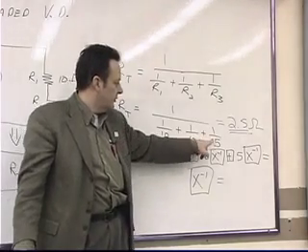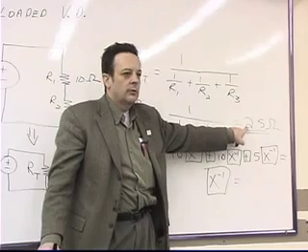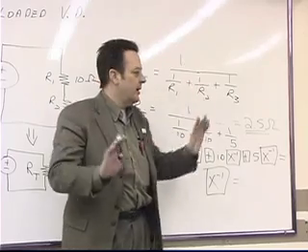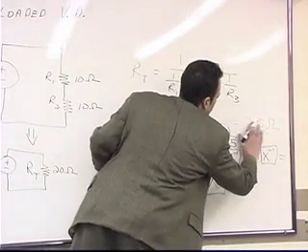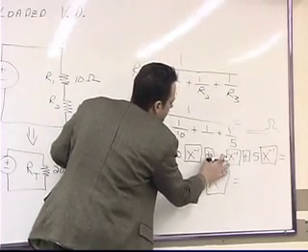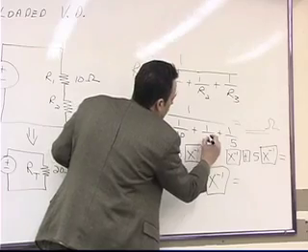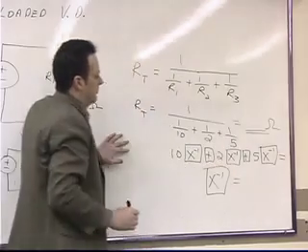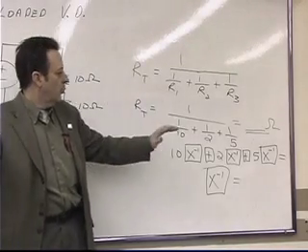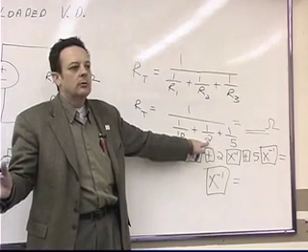Do you notice how the smallest resistor in the circuit was a 5 ohm resistor? And what did we come out with our total? 2.5. Okay? So if, let's just say, hypothetically, I were to erase the answer and change this 10 to a 2. Before anybody tells me what the answer is, what do we expect the answer to be less than? 2.